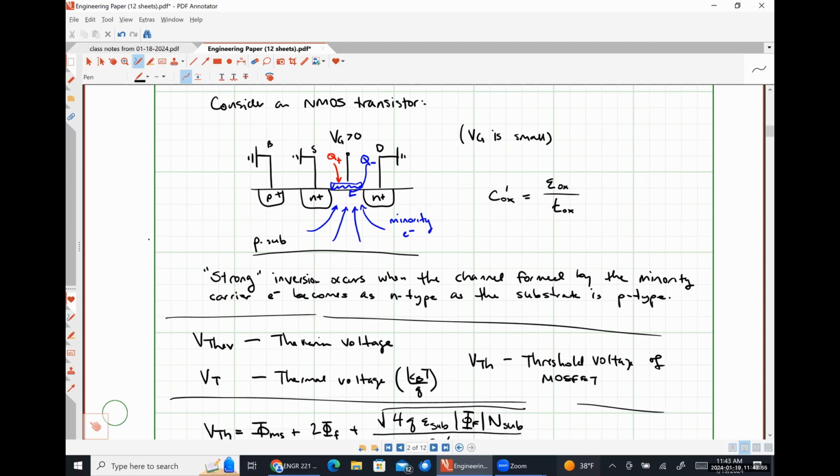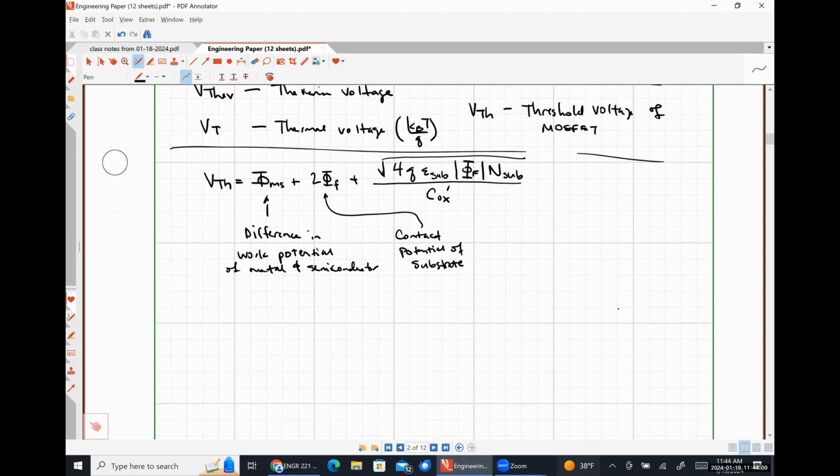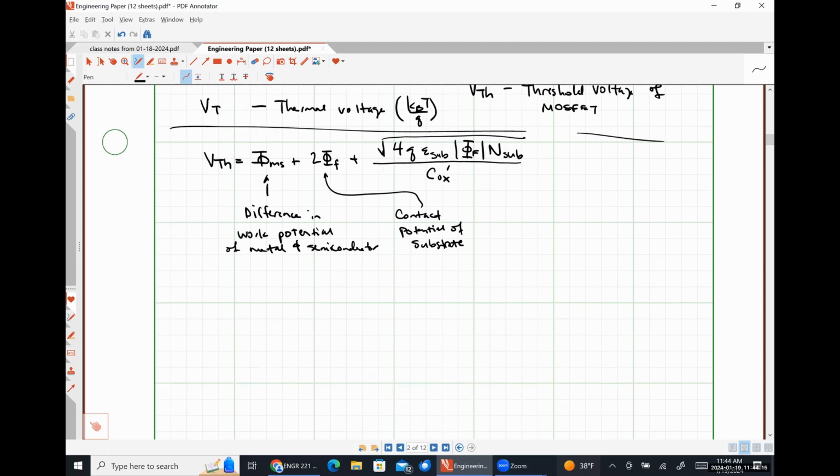All right, so threshold voltage taken care of. Effectively, if our gate voltage is not greater than our threshold voltage, our device is off. No currents flowing anywhere. Now let's talk about body effects.